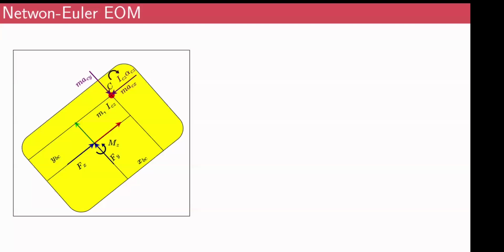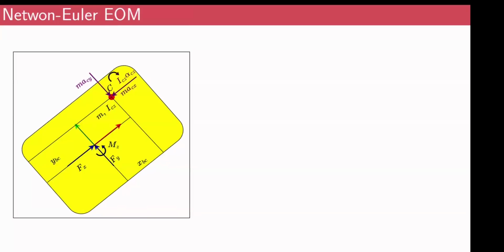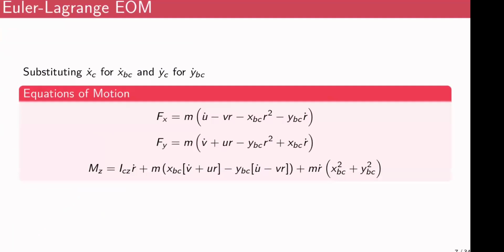And the reason that we go with the Newton-Euler approach is that it gives you much more insights. For example, earlier in the Euler-Lagrange method, you only got the forces Fx, Fy, and Mz, right? Because it's a mobile robot that basically lives in a plane. Other coordinates are not relevant.